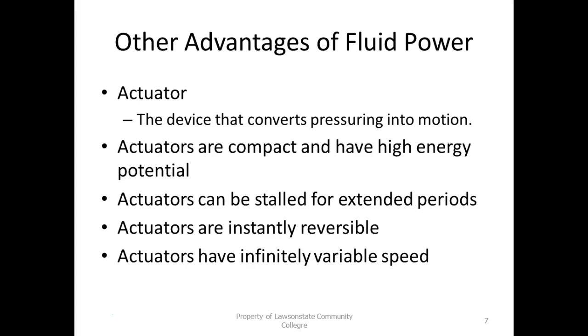Huh? Yeah, but you're going from a combustion engine over to something else, right? So we're talking about a fluid power actuator. Fluid power actuators don't really need clutches because we can stall them; it doesn't hurt them. Other things like a combustion engine hate to be stalled, right? You understand? Even though I just stalled my motorcycle one time. That was embarrassing. You never did that though, did you, John?